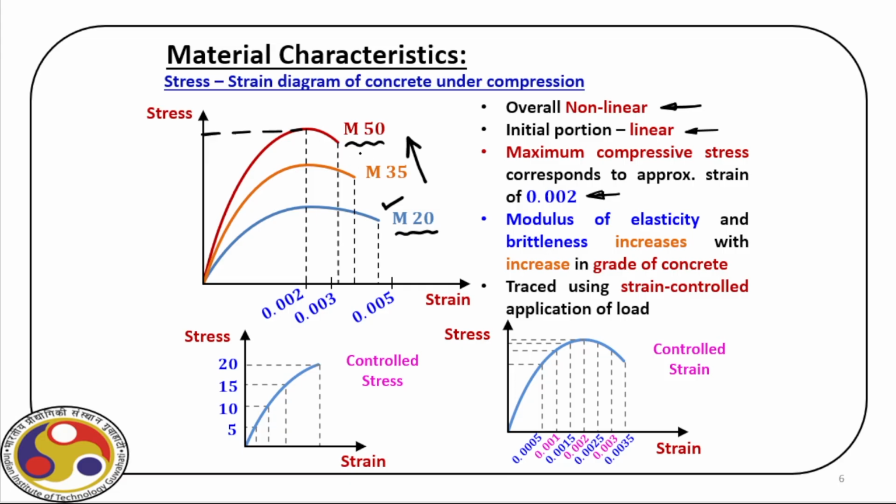So we have this nonlinear behavior between stress and strain, and the main point here is this one. And also one more issue is there. We consider up to 0.0035, and that's the strain level we always refer to at the time of failure. We'll come to that in a minute when we draw the block diagram.